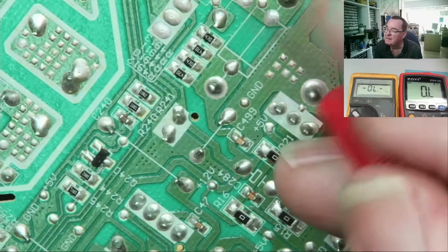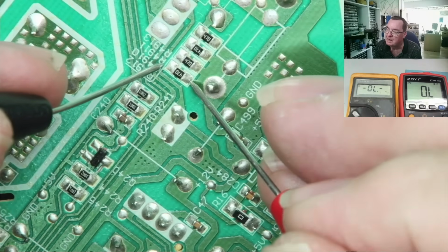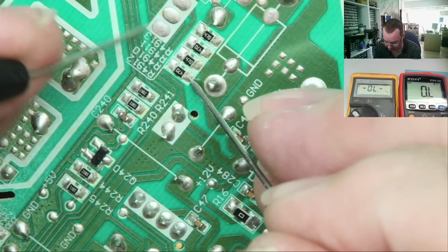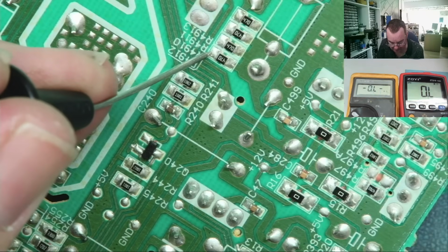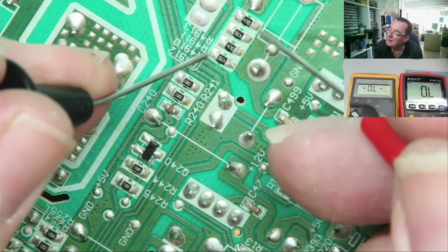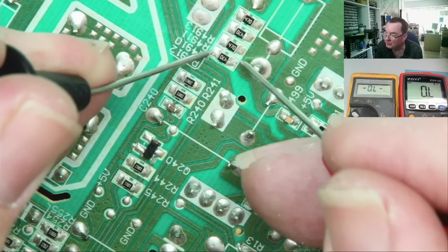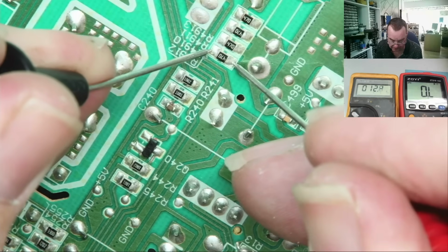Also, don't make the beginner's mistake. You think these are all 470 ohms. They're not. They're 47 and 0 zeros, which is 47 ohms. They're also in parallel, and they'll read very low, about 12.5 or 12 or something like that, 12.4. I just worked out what they were going to be.